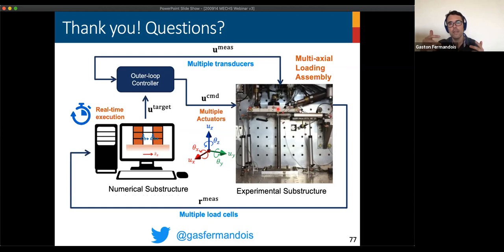And these 8 actuators were chosen such that you impose the displacements and the forces in a certain way, right? Why 8 and not 6? Well, that's basically the approach of the University of Illinois by designing the load and boundary condition box. You need at least 6 actuators in order to have a parallel manipulator, a redundant system, in order to impose a 3-dimensional rigid body motion at one point.